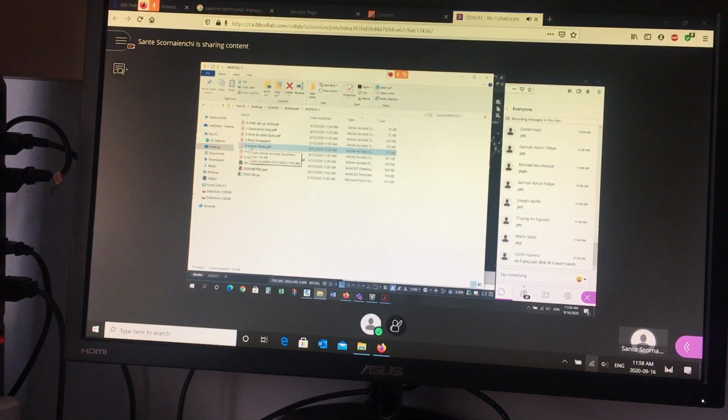So if you had to do something quick, and you had a template that had all this already programmed, you can see the power of having description keys, point styles, point label styles, and groups ready to go. Okay? But you have to create that. By doing the work, you can appreciate what they are, so that if all you're going to do for the rest of your career is use them, you can at least understand what they are and what they do. So that's the purpose of this.